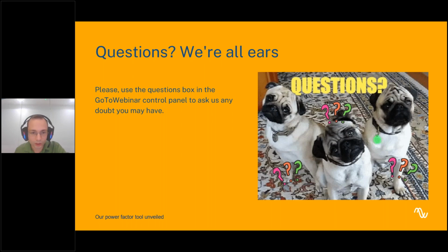Okay, so one question is, will we be able to manually size the capacitor banks in pvDesign? Yeah, so right now we are going to give the option to decide which equivalent systems of the software will be compensated by the capacitor banks. So you will be able to say, for example, I want the power transformers and the MV lines to be compensated by the capacitor banks, but the power stations I want to be compensated by the inverters. And you can play around with the tool to establish the configuration for reactive compensation that you want.